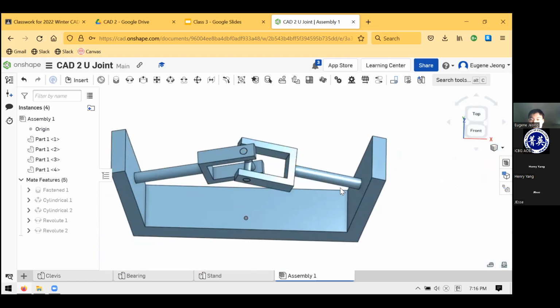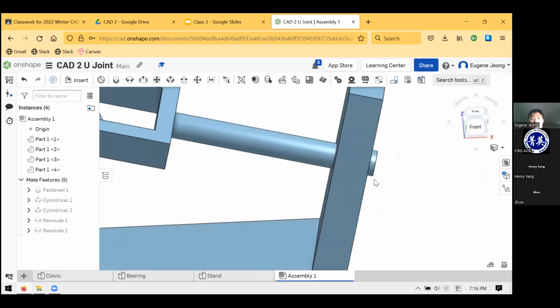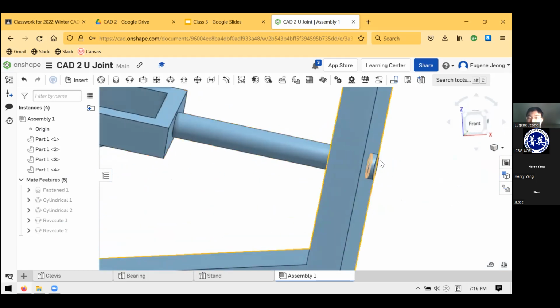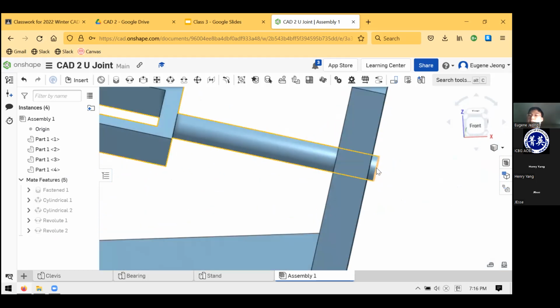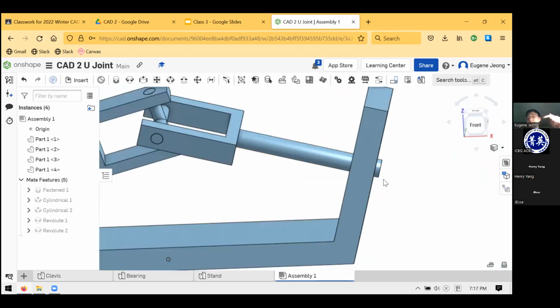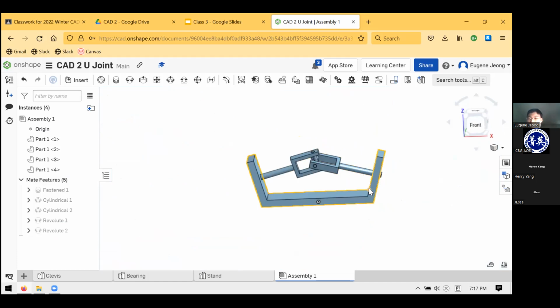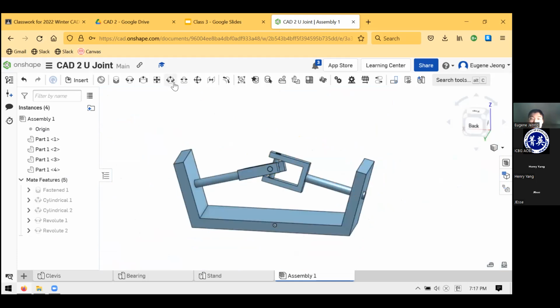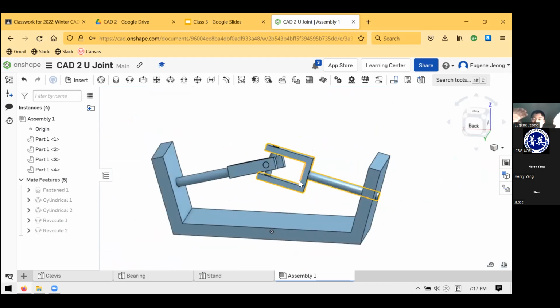you can see this is what I was talking about with not knowing exactly where the rod is going to sit. If I'd started out with Revolute, I would have had to specify this exact distance for where the rod needs to stick out. And I didn't know that because I didn't do the math. So since I used the cylindrical mate, I didn't have to worry about it. I just left that degree of freedom. And now that everything else above it is constrained, it just works itself out.